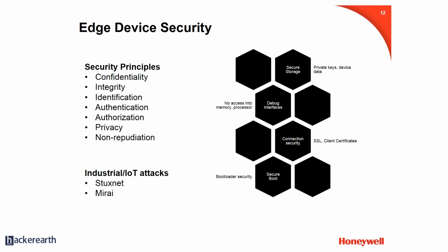So some of the things that we have to address, right? One is you'll have to make sure that your embedded device has secure storage. For instance, if you're using any keys to encrypt your data, and that key is leaked out or somebody can read it, then you're in effect compromised, right? So you need a secure storage where the key cannot be read out by anybody.